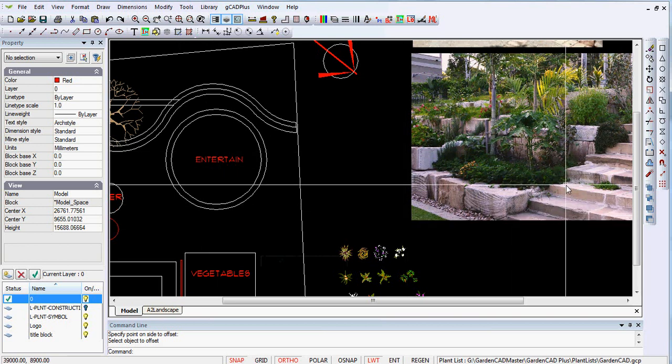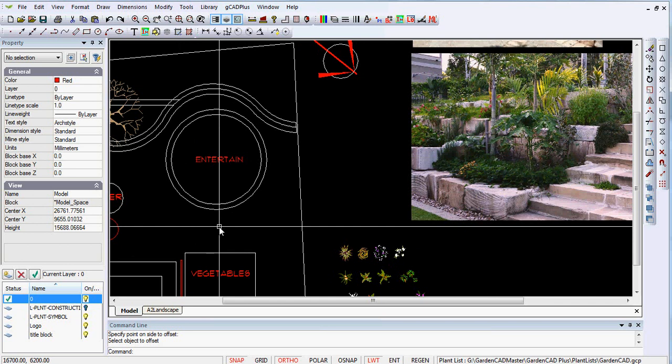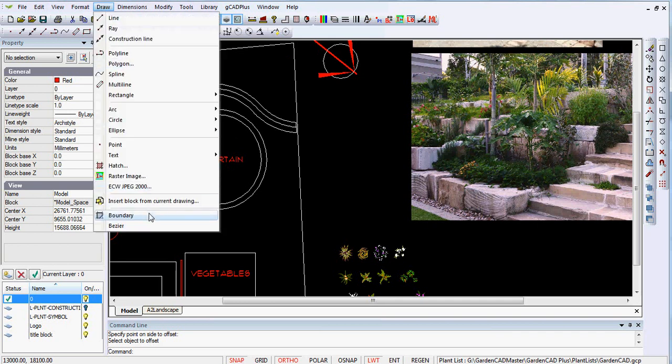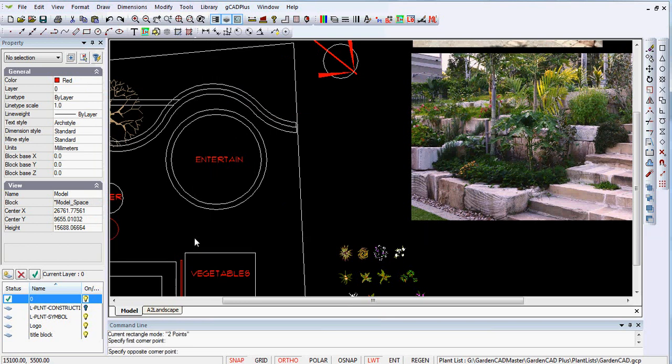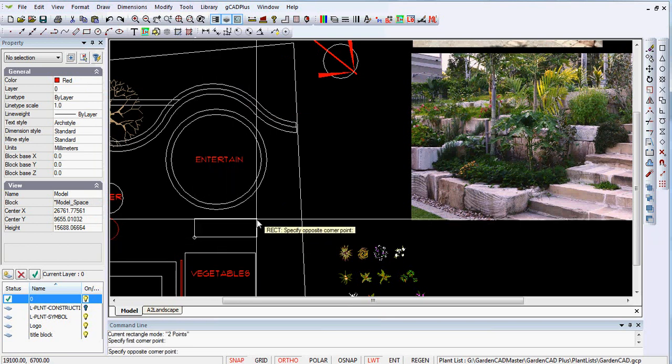So there'll be some steps similar to the ones shown on the right, and my constructor likes constructing these steps out of the length is usually 2 meters by the tread width of 400. So what we'll do is pick the rectangle command, draw a rectangle with 2 points, and we'll just arbitrarily pop one down here and then move away. Now, for this we use relative coordinates, the at sign, at 2 meters in the X and a comma 400 in the Y, and enter.